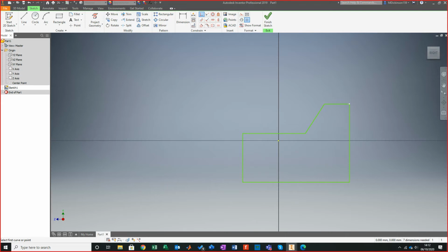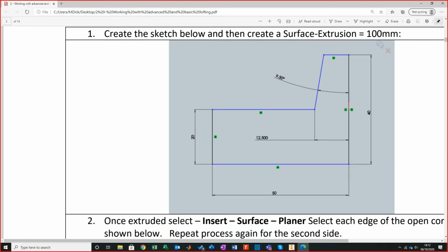I'm going to the end point there, or there. Now with SolidWorks, you need to define exactly where you're coming from. However, if I move up the line, it'll pinpoint there and automatically select me a midpoint. So it's a little tool that I do actually quite like. So that's now got me that line.